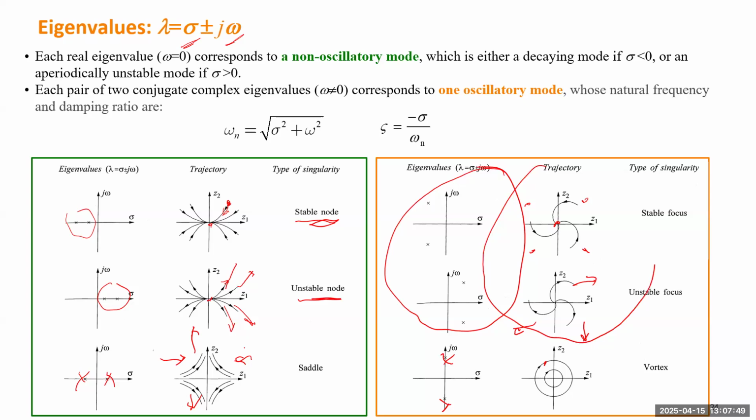We want to check whether each oscillatory mode is stable or unstable. Okay, so if it's unstable, we definitely need to do some control. If it's stable and we want to make it even more stable, we can design the controller to push the complex eigenvalue further to the left. That will increase damping. That's what we want to work on in the next few slides.